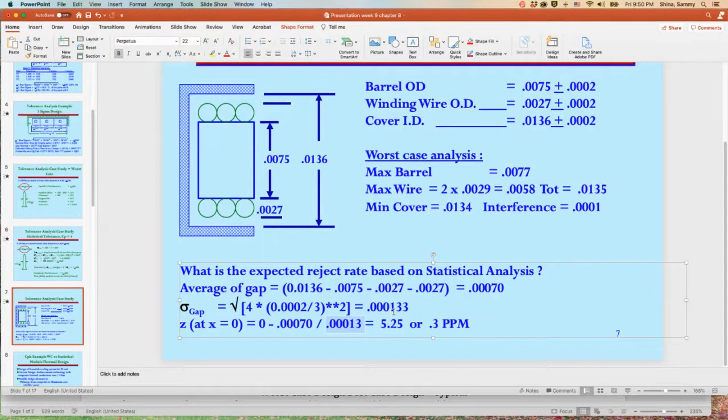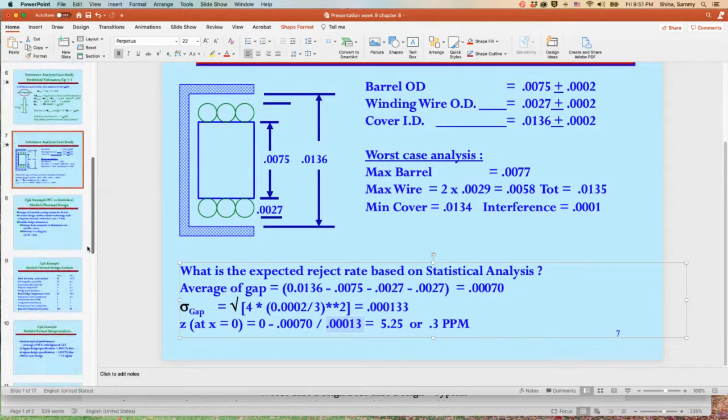The catheter heads vibrate. So that's another interesting way of using tolerance analysis as opposed to worst case analysis, and then predicting the reject rate beforehand, something that the company can tolerate or the designers can tolerate.